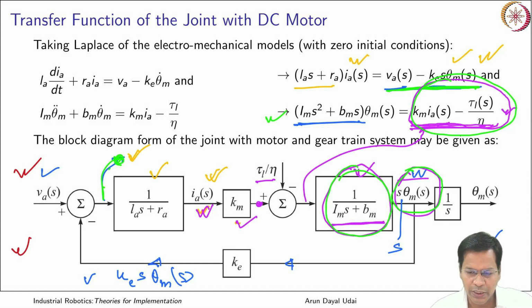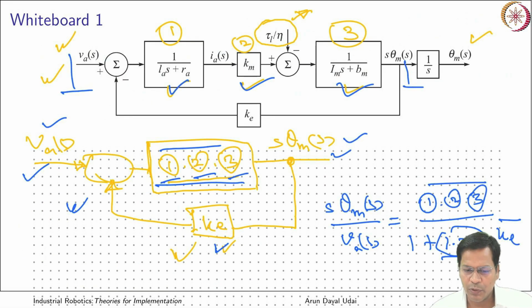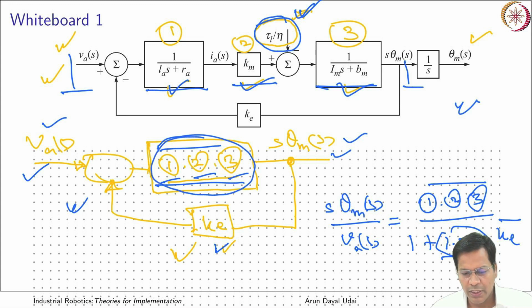So these two equations are clearly put into this transfer function, and the whole of this can now be compacted using the approach that I have discussed here. So I will make a transfer function of all of this. In the first case, I am excluding the disturbance which is coming from outside, that is this term, taking the product of all these three and creating a closed loop over here with this one as the system.